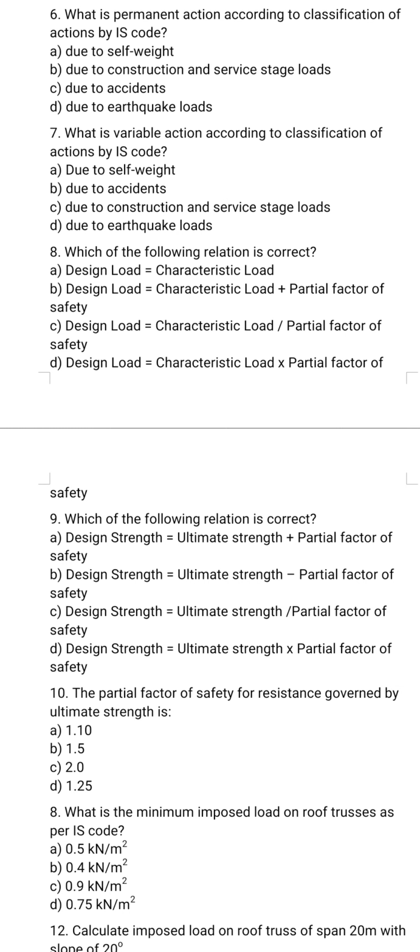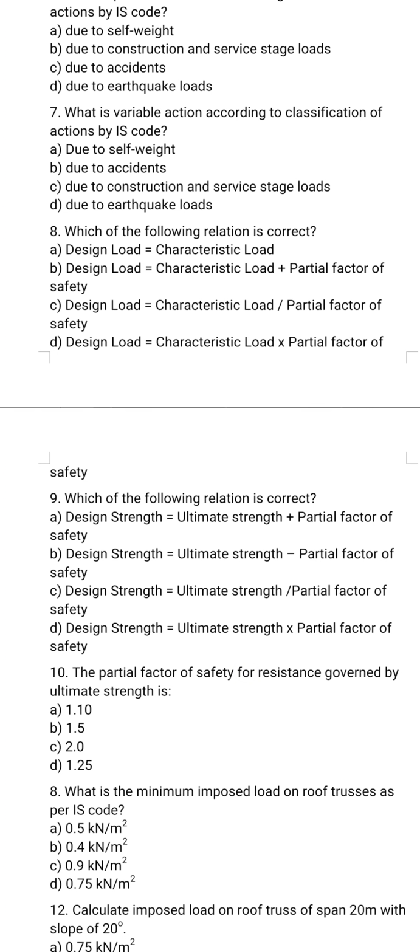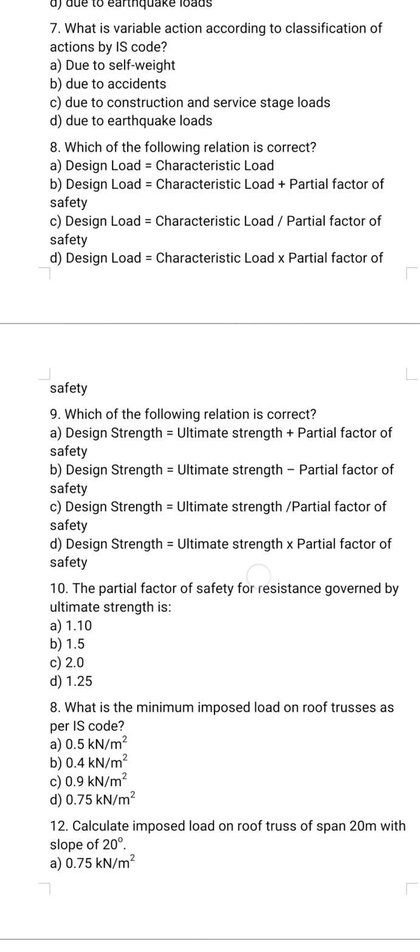The partial safety factor accounts for the possibility of unfavorable deviation of load from characteristic value, inaccurate assessment of load, uncertainty in assessment of effects of load, and in assessment of the limit state being considered. So basing upon that, your answer should be option D.